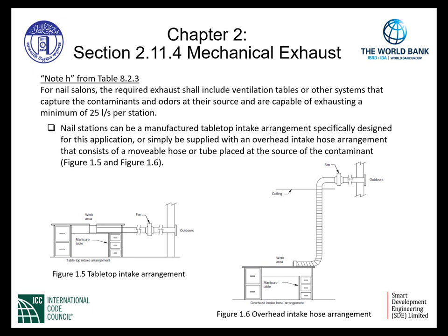As seen in Figure 1.5, this is a tabletop intake exhaust arrangement. At the work area shown on the tabletop, this is where we would get a minimum of 25 liters per second per nail station. As shown here, we have an inline fan that draws air through the inline fan and directly to the outdoors.